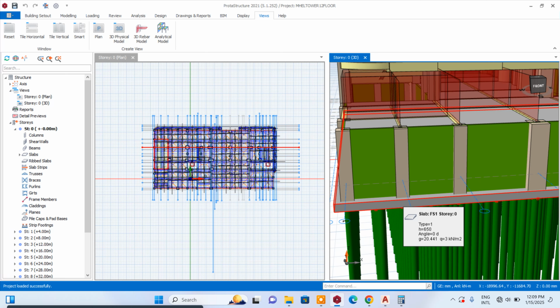You may use a raft slab on beam or a different type of raft design. And if you discover that the raft is not giving you the expected result, you can switch to piles. And if you discover that even piles cannot give you the result you want for your design, you adopt raft on piles. You design for raft, and after that you design for your piles.